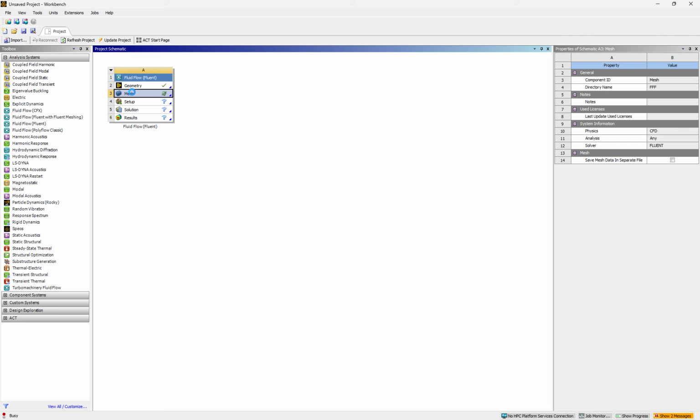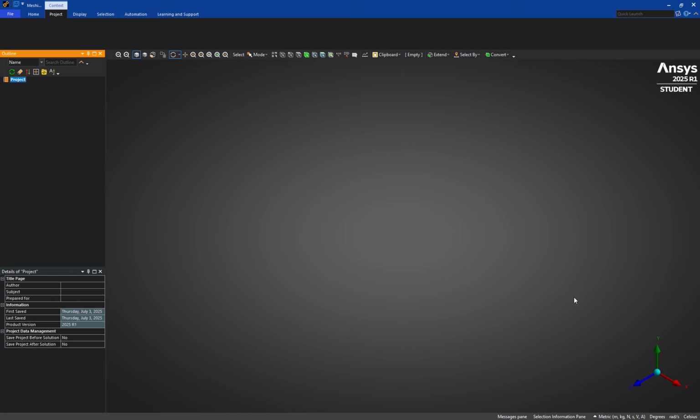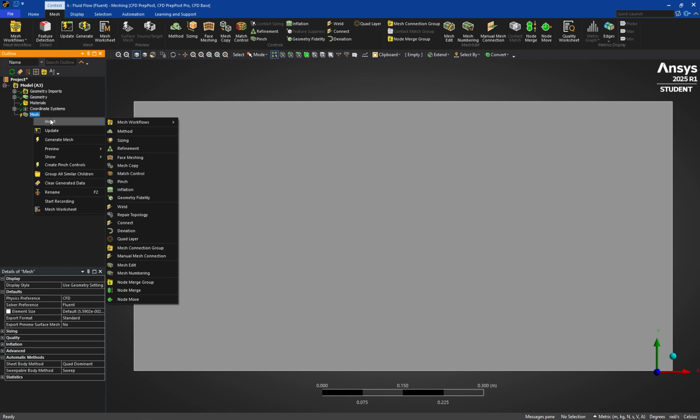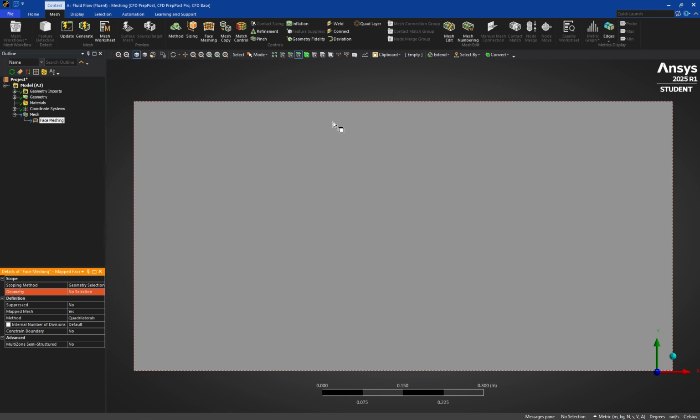We cannot really use this mesh, although it's the default of the software, because it does not have the characteristics that we want. For example, we know that near a solid boundary there will be a huge gradient of velocity, very sharp changes of velocity here. So we want to have more grid points near the surface because that includes the high gradients. Therefore, we need to modify that. So I can click on mesh and go to insert. Okay, there we go.